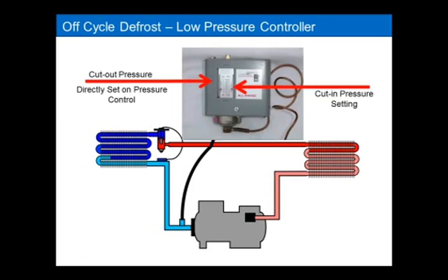There are some pressure controls out there, not a lot, but there are some that do allow you to adjust the cutout value directly. So keep a watch for that. They always allow you to set the cut-in directly, but there are some that allow you to adjust the cutout directly as well.